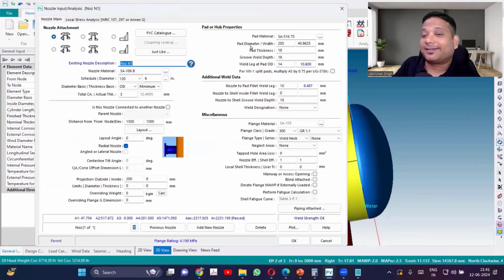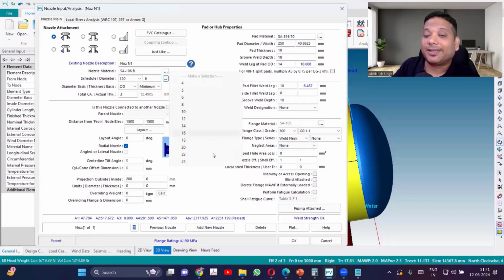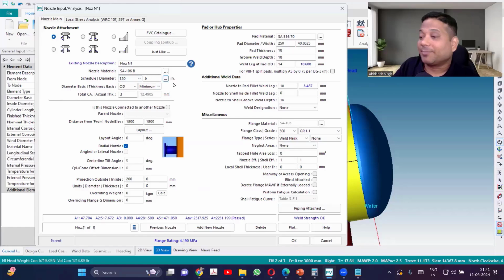RF pad here, you can see this is the place for RF pad. Just keep the thickness of the RF pad equal to the shell thickness and diameter as twice that opening, and you'll be good to go. You'll also be able to see the area required and area provided. If you're asking about flange, then yes, 16.47 is what you use for more than 24-inch. If you're asking here, then you have to create that by using a nominal, without using this option, and giving the actual size.